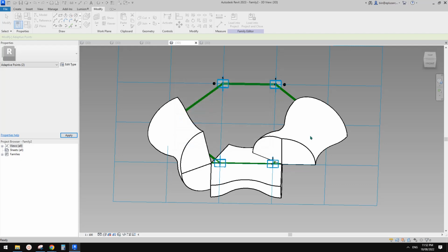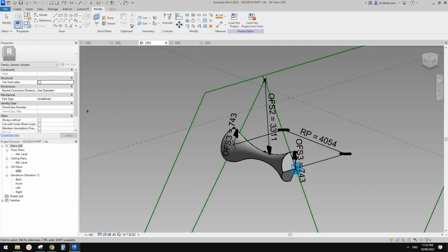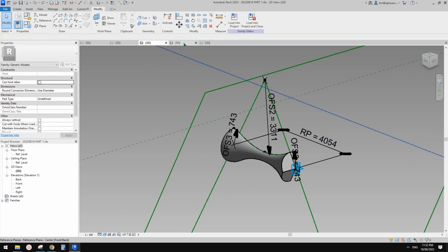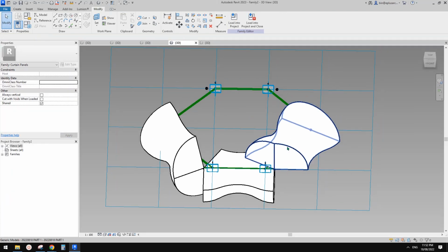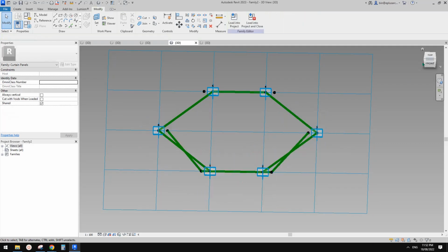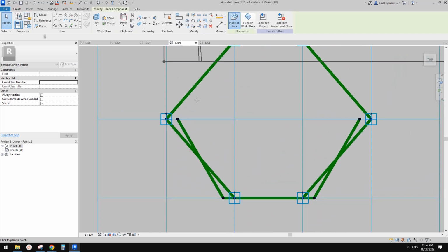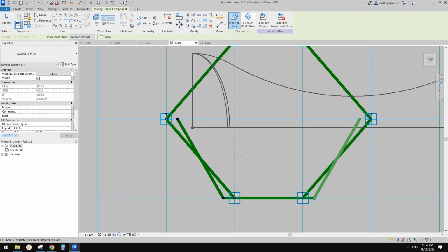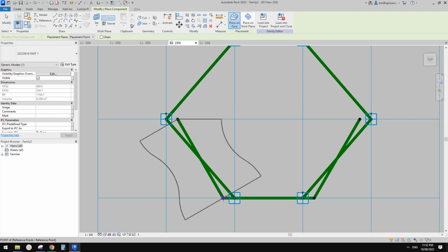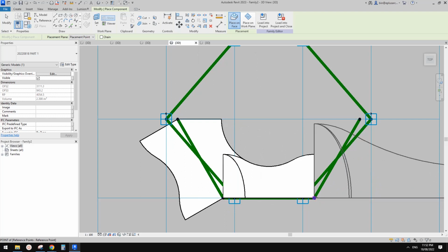Override. Oh. Okay, it breaks it. Let's go back. Control Z. Change it back to instance, but we can still try to figure out how to place them properly. Actually, I'll go to the top view of this, and without trying to tab or select, I just pick here, on the first point I can snap onto, and here, and this one, and this one, and this one.